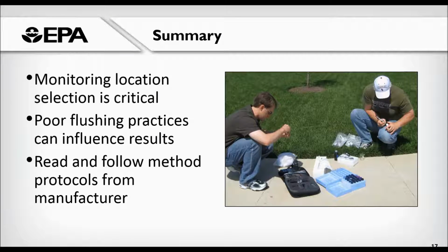Also, adopting a technically sound sampling approach is an important aspect of collecting reliable chlorine residual data. If the sample site is not flushed in an appropriate amount of time, chlorine residual cannot be accurately characterized. And also, field methods aren't perfect. Like any methods, they're prone to certain interferences or limitations. However, you can still obtain accurate, reliable results if you're familiar with the nuances of the method. Just because a colorimeter gives you a number doesn't necessarily mean it's an accurate number.